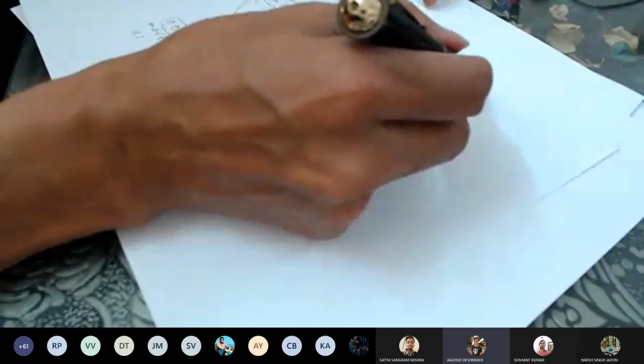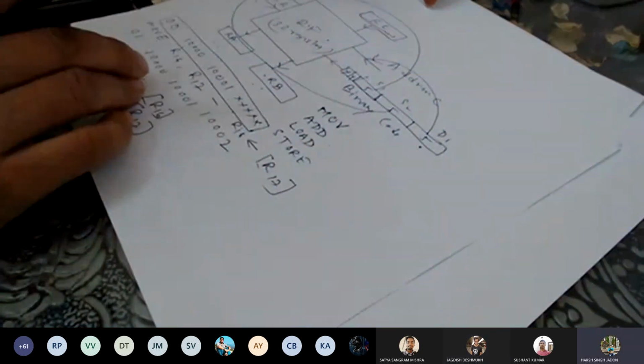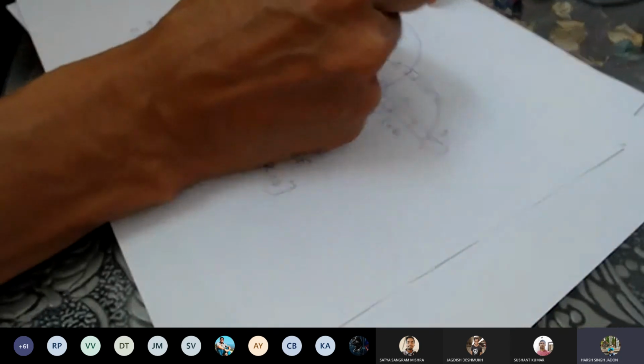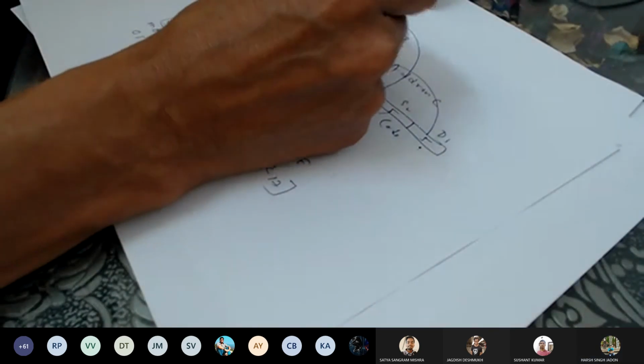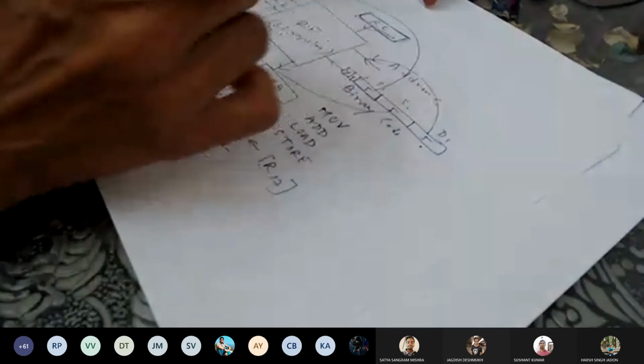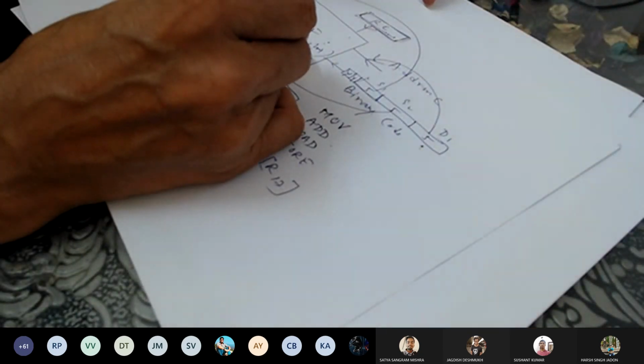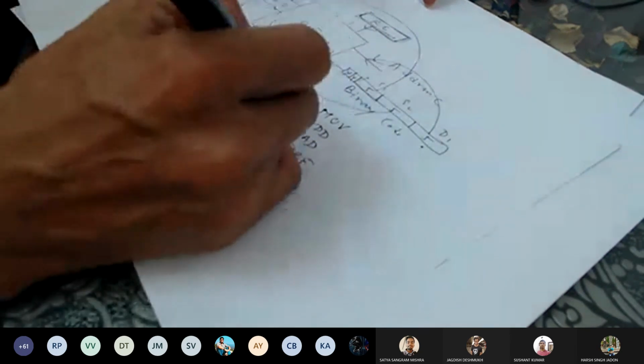Store is basically coming outside to the register file. Got it? RC is like a value. RC will be given as a value, na? RC is an external register. These RA, RB, RC are 3 external registers other than these 32 registers. So you will have to implement these 3 registers also.